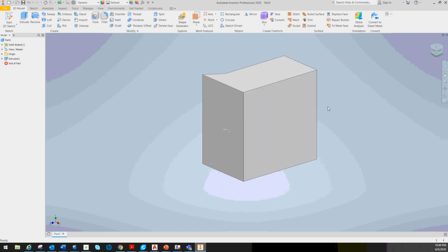Once we click OK, now what happens is our original sketch that we did, all of our dimensions in the sketch is now gone. So our extrusion consumed our sketch. There is a way to bring it back if you need it for anything, but what would happen on elaborate objects is if you kept all your sketches, it would really clutter up your drawing.